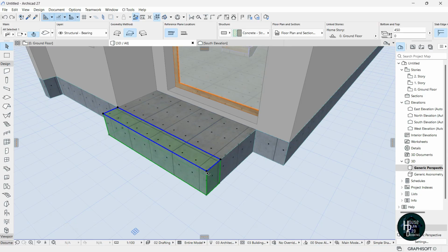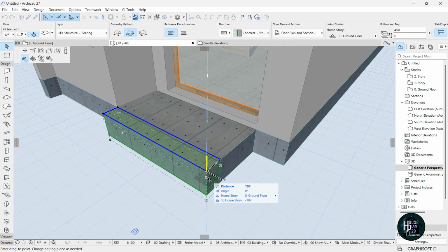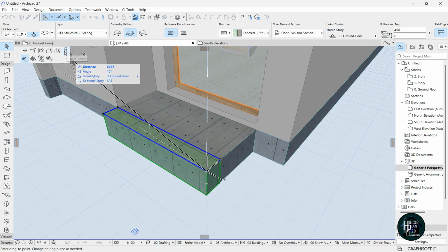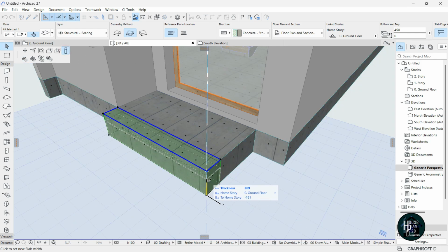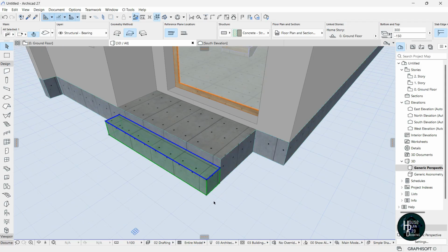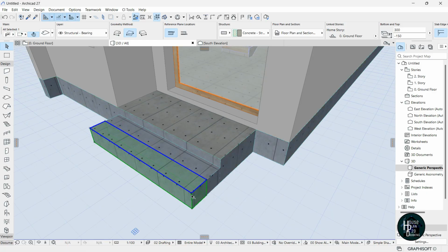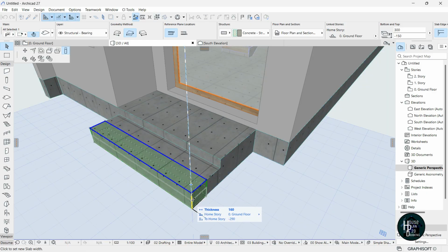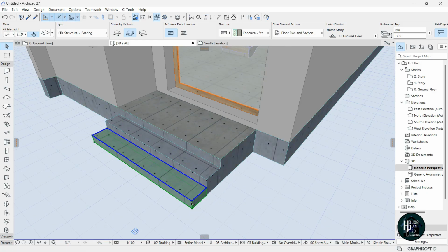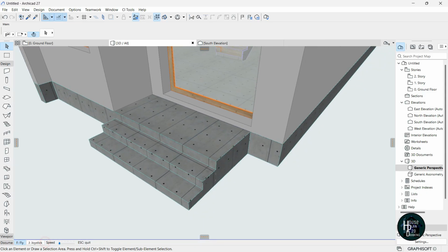this one, I want you to come here, click this, reduce this by clicking on this stretch height, click this, and let's try and reduce the height of this to be 300. Click enter. Alright, now press Ctrl+Shift+D, click this node here, move it to this front here, click on this stretch height, bring it down and give it a distance of 150, click enter. Okay, now I'm going to be having something like this.